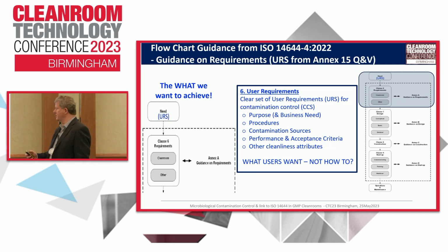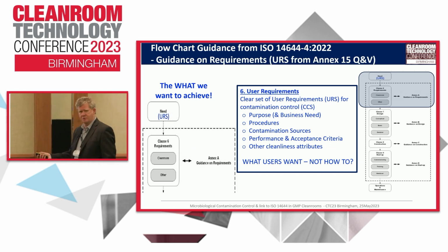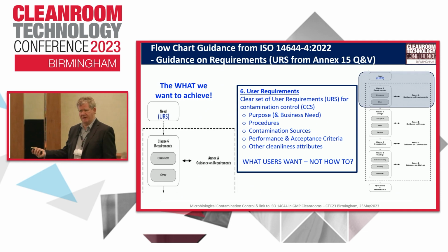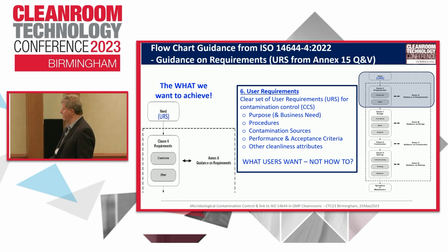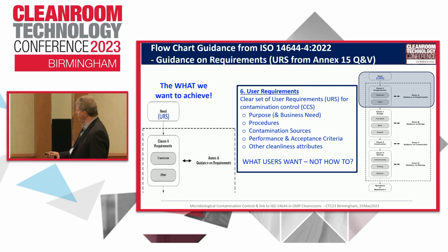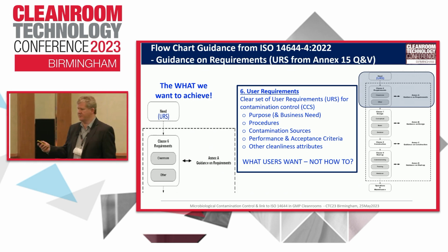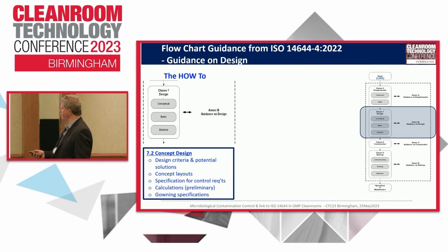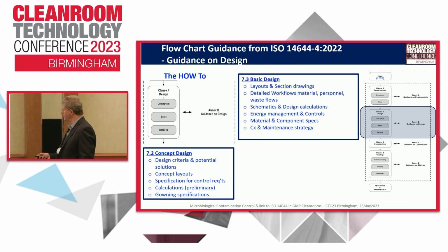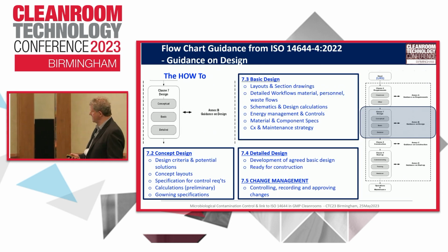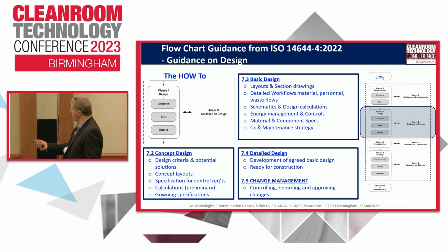You talk about the process. What do we want to achieve in the clean room? What am I making? Why am I making it? What are my regulatory and accreditation requirements? So what's the purpose, the business need? Other attributes: what the users want, not how to. Guess where the how-to comes in? The how-to comes from the concept design, the basic design, and the detail design, and you're in this continuous review, which comes from the standard on it, okay?